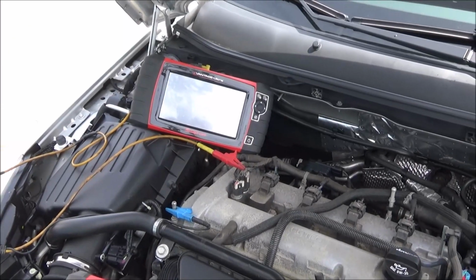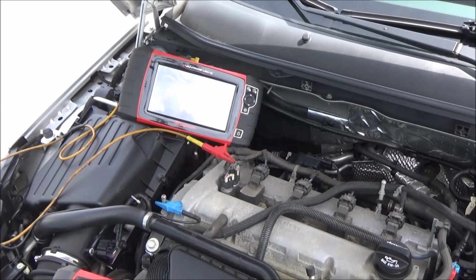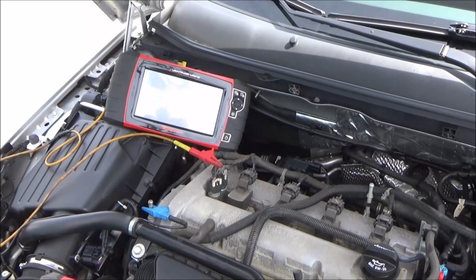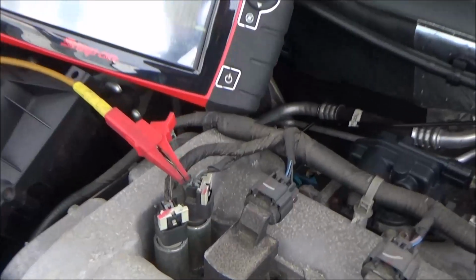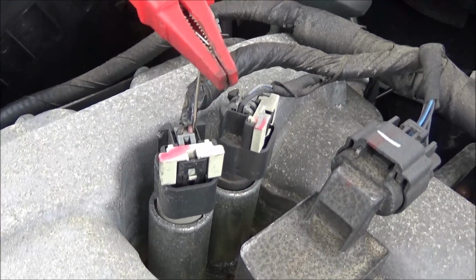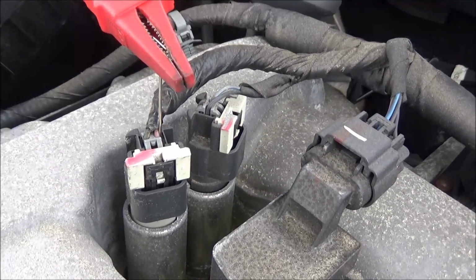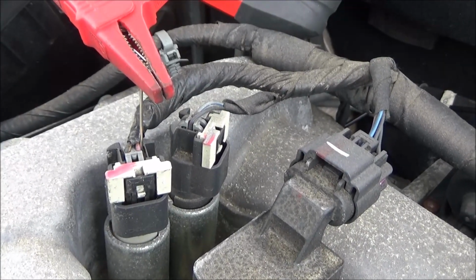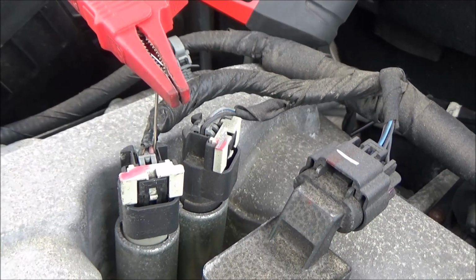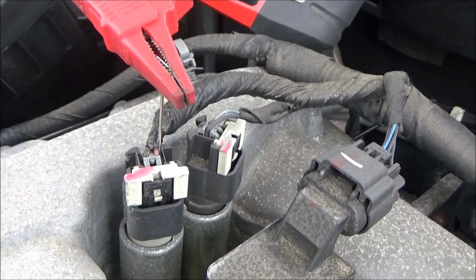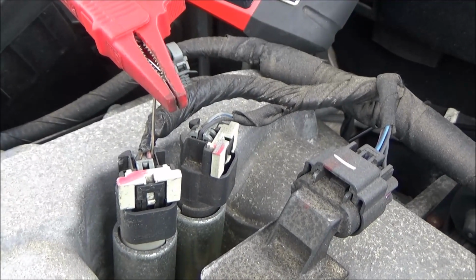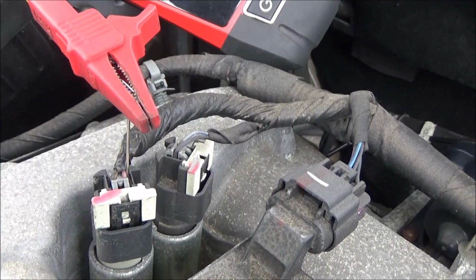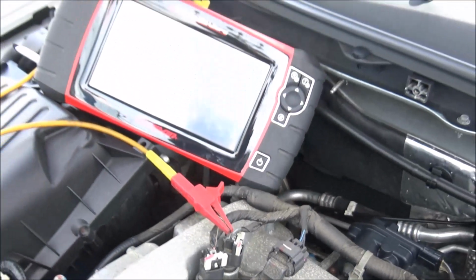Alright guys, this is the basic setup here that we're going to use to check this intake cam solenoid. I just have a T-pin going to the positive side control wire in this solenoid here. If we look at this solenoid, we see two wires coming off of it. The one we're currently hooked into is what appears to be a pink with maybe an orange tracer. And the one to the left of that is a black with an orange tracer. This black with an orange tracer is basically the solenoid ground. And this pink with the orange tracer is going to be the power feed to this solenoid.